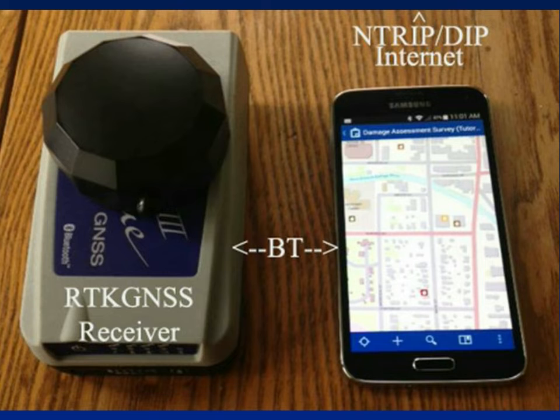So the wireless network of the mobile phone would access the RTK base at another location, right? Could be 5 miles away, 10 miles away. And this is the hardware you would need to take in the field: a receiver, an antenna, and the mobile phone. As far as the receiver goes, there's different flavors out there. This is just one I had handy. I took a picture of it yesterday. But there's others out there. Some have integrated antennas inside the receiver, so it's not a separate device. And there's several manufacturers out there.